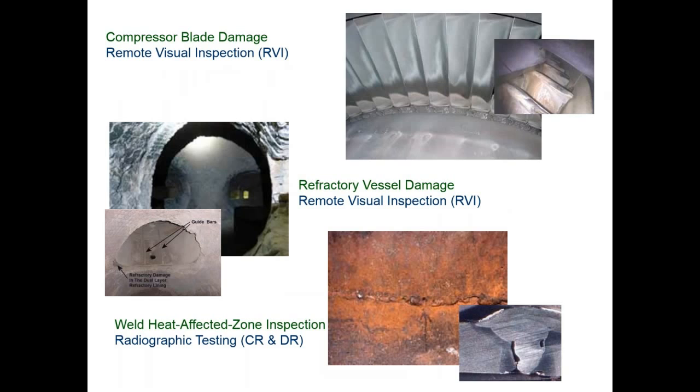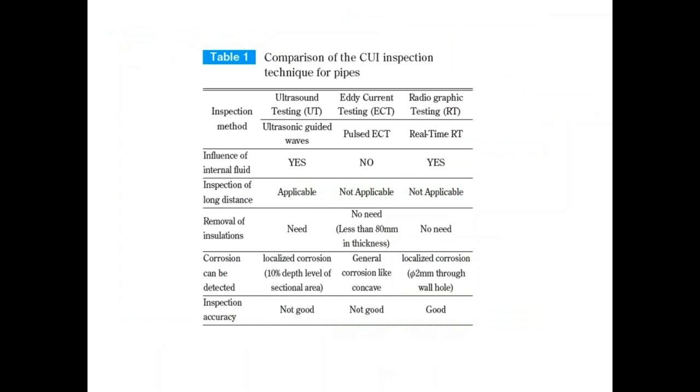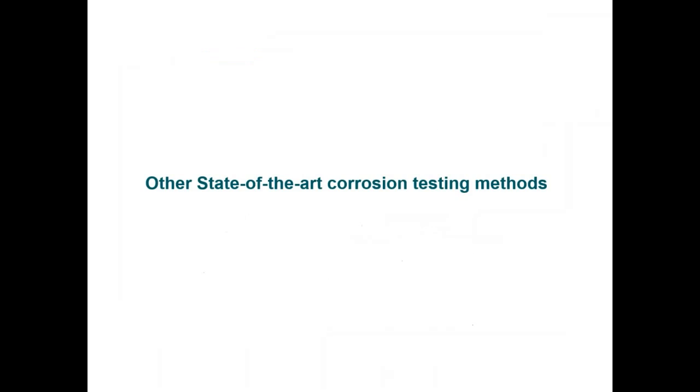Okay, so these are traditional inspection methods which can be recorded, evaluated, continuously monitored, and set up as a program which can either be a risk-based inspection or periodic-based assessment. CUI, as I mentioned, is a common problem, and these are some of the techniques and their advantages and their specific parameters that can be tested. Again, I'll be happy to go back to this table.